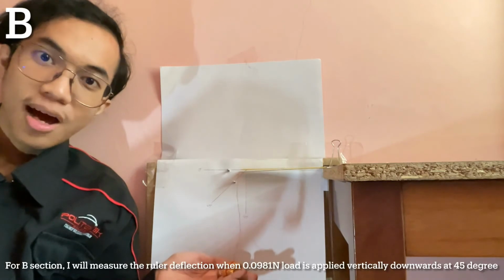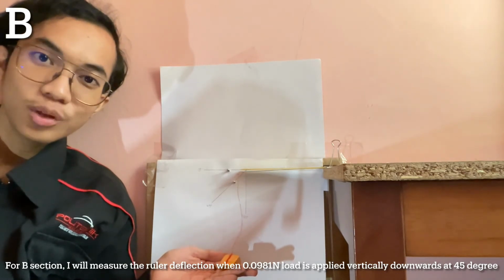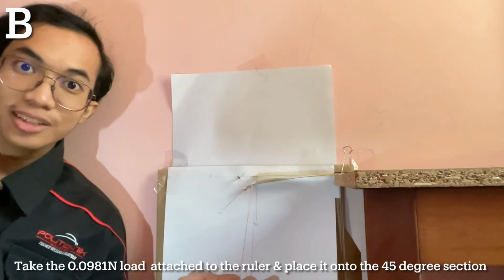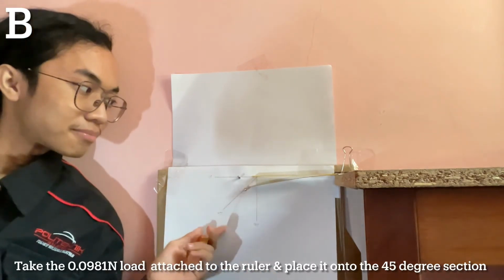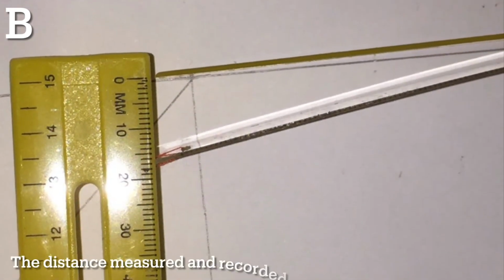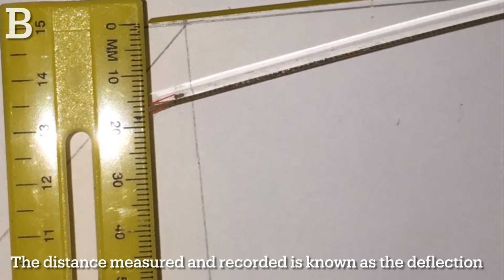For this section, I will measure the deflection of the ruler when 0.0981 Newton load is applied onto the ruler vertically downwards at 45 degree. Take the 0.0981 Newton load attached to the ruler and place it on the 45 degree section. Now, measure the distance from the initial placement of the ruler to the deflected ruler. The distance measured and recorded is known as the deflection. In this case, the deflection is 16 millimeters.